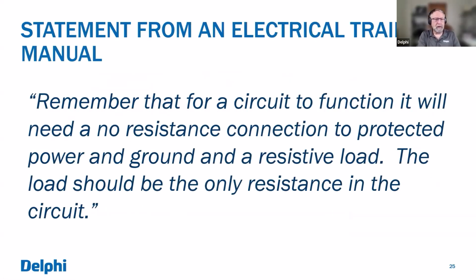Here's a statement from an electrical training manual that I saw in the recent past. What it said was, remember that for a circuit to function, it will need a no resistance connection to protected power and ground and a resistive load. The load should be the only resistance in the circuit. And if you think carefully about this, if you have better information, and I say that with love and respect, well, the load isn't the only resistance in the circuit.